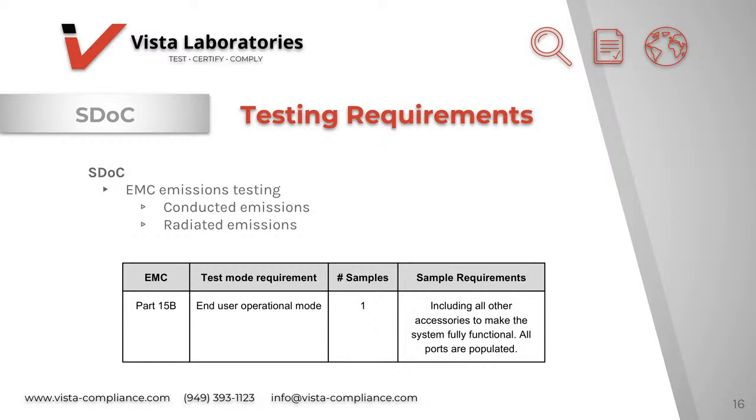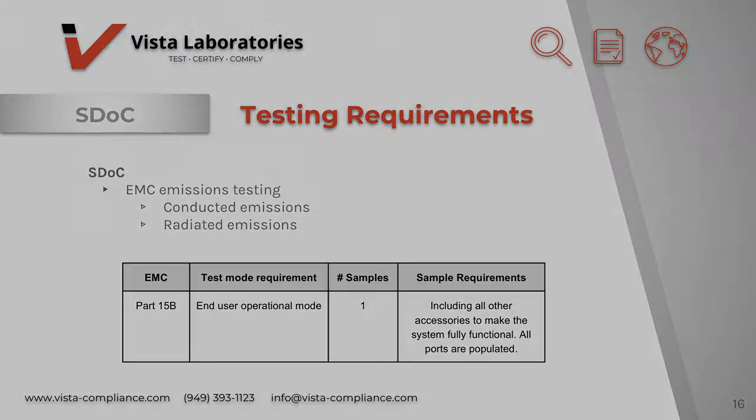Conducted emissions is required if there is an AC power supply included or Ethernet ports. All ports must be populated during testing. Radiated emissions is required for all devices.